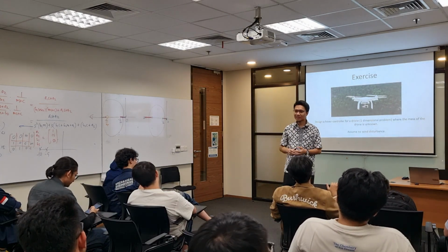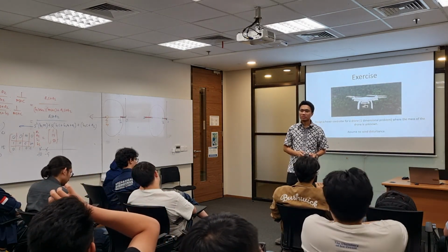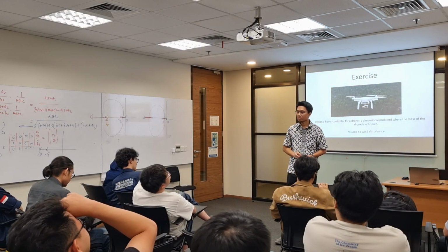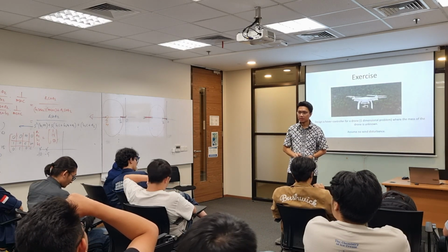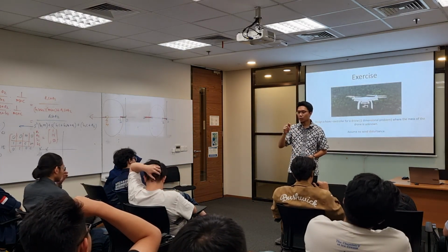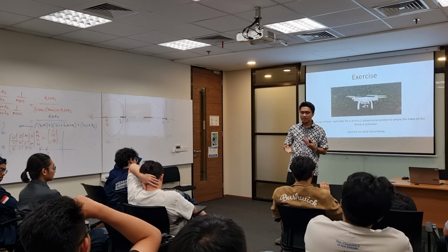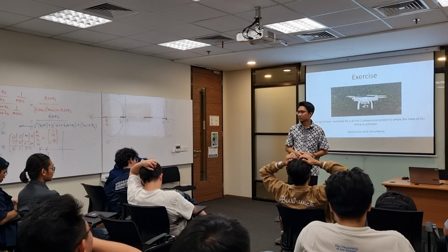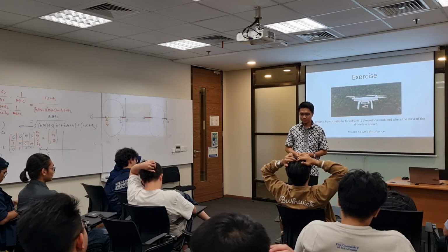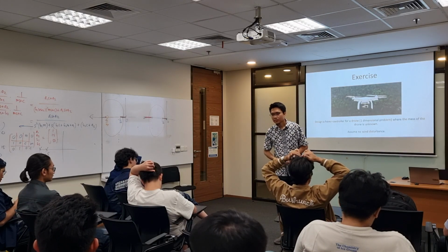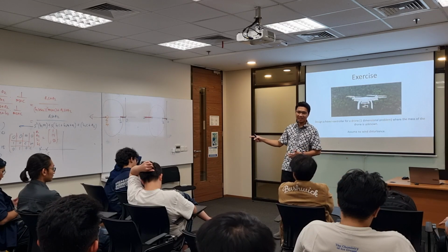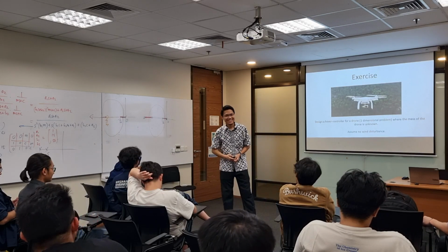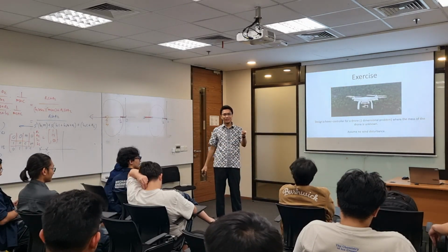So these are all related processes. The approach of setting the poles by setting omega and zeta is the same. Because you are setting omega and zeta, you know what will be the overshoot, what will be the settling time, right? We are just translating them to omega and zeta. Which makes it very easy, right? You know already, it's easy, right?